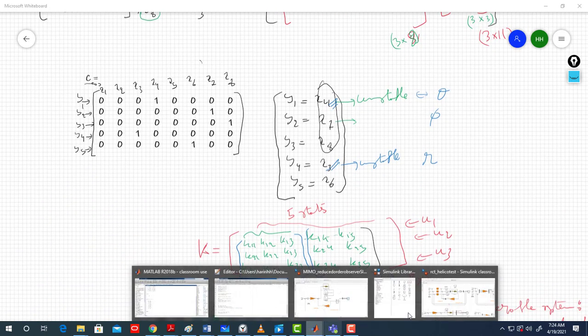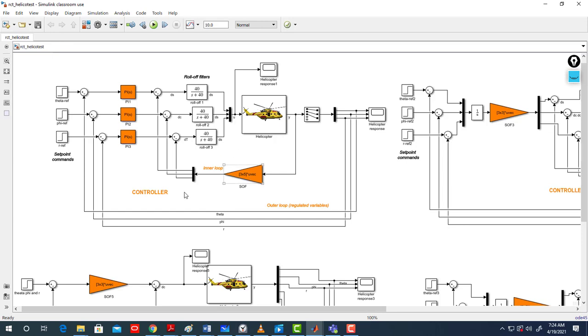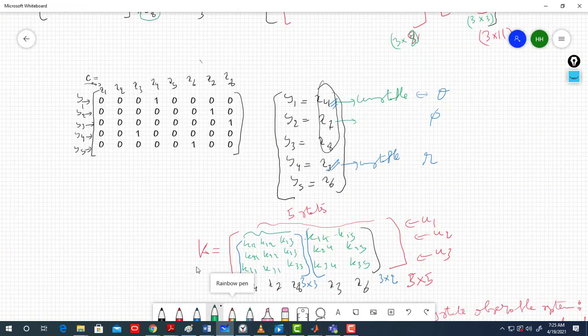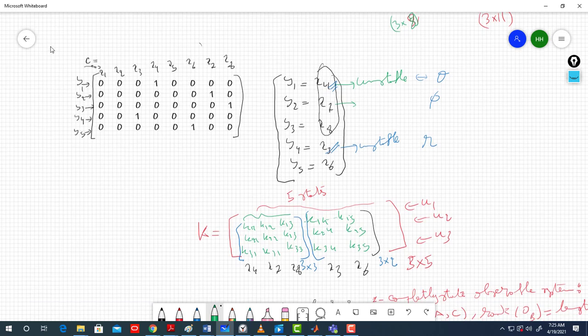You remember last time, you can go to the Simulink model. That's the one proposed by the MATLAB tutorial. They feed the 5 states and they control 3 of them. And what are those 5 states? We were looking at them by looking at the C matrix, to see which 5 states out of 8 they are feeding. At least we are sure they are feeding the unstable state. So this is very fundamental. You should feed them in the state feedback. Later on, for the output, it's up to you, whatever you want to track.